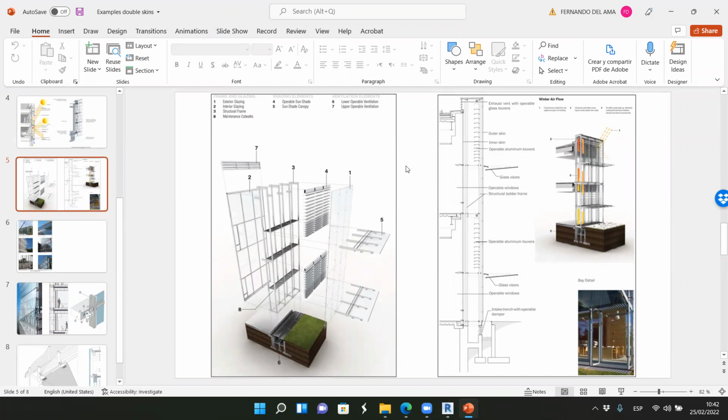But if we are creating or designing the sheet itself, the page, we need to make sure that we have 2 or 3 maximum different font types. We can have something for the title of the drawing. We can have something for those details, or something for these numbers, and something for the letters, but no more than 2 or 3 types, and we have to be consistent.